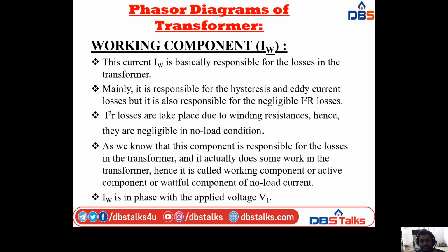As we know, this component is responsible for the losses in the transformer, and it actually does some work in the transformer. Hence it is called the working component, active component, or fractional component of no load current. We have so many names for this one.